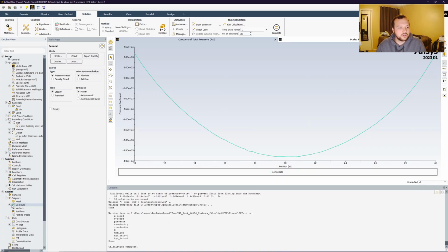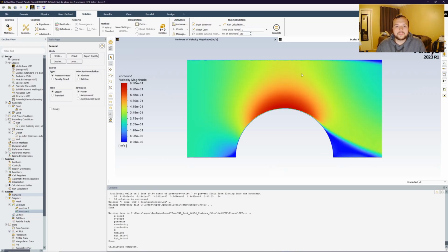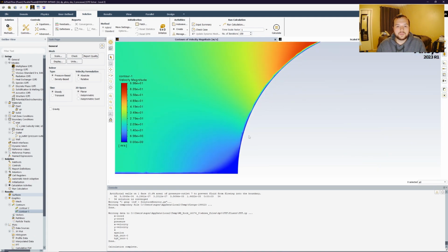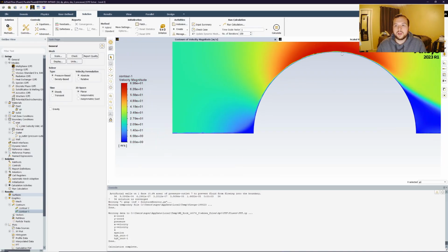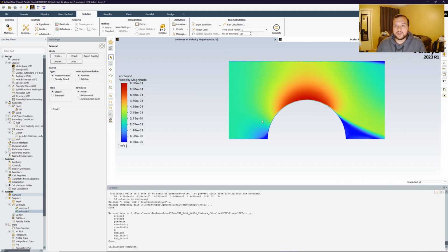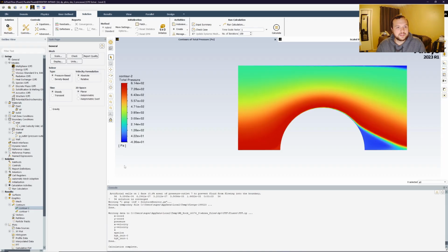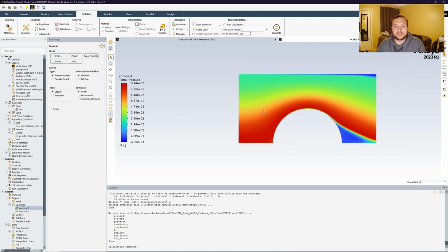And again, just to show the differences, we'll just go to the first contour here. So this is the velocity, right? Again, it's viscous, so the no-slip treatment is there, which is highlighted when you see that blue going across the line. And then the formation of that wake region back behind here. And if we pay attention to the top, you see a kind of a boundary layer forming. So the procedure is exactly the same, and that's how you do part 3 for the project.